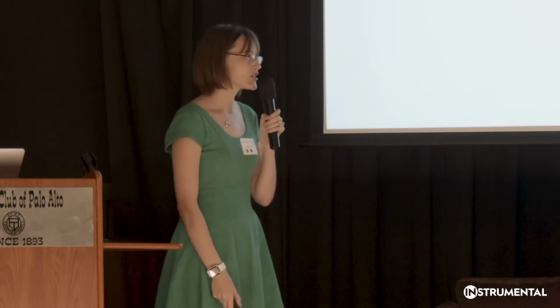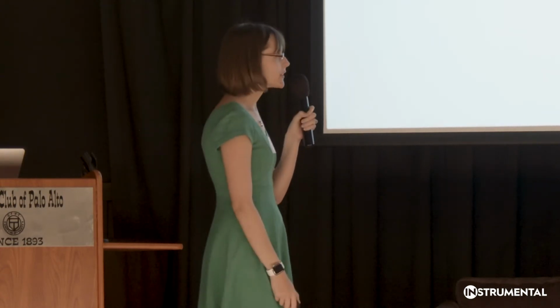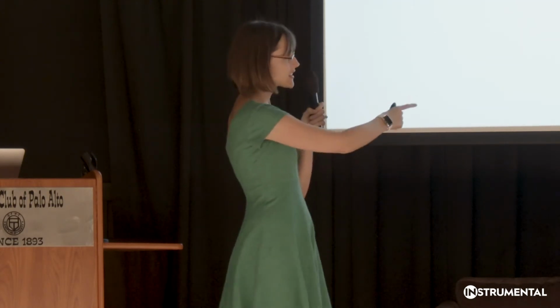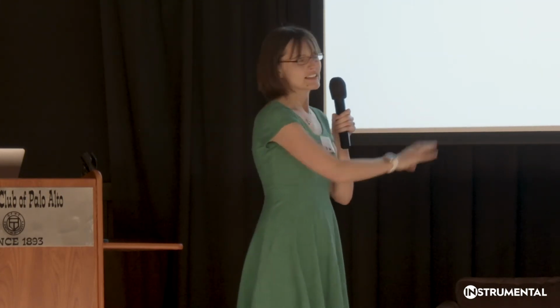So throw back to your sub-suppliers and needing to keep an eye on your sub-suppliers. This had gone through a ton of human inspection. It passed all the functional tests, but this actually creates all sorts of concerns and problems because they're going to put these units in their REL tests and they want to validate the design. And if it looks like this going in, it seems dicey whether you want to build with those parts or not.